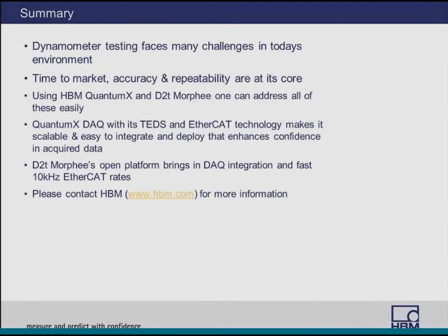The only thing is today we can communicate directly with the ECU. So that means the ECU is usually running at up to 10 kilohertz, maybe more. So we need to communicate with that ECU very fast. Also, we have other applications such as the simulation or the models which are running at a very high frequency. So in order for those models to perform fine, we want to run at a very high frequency, and that's why 100 Hertz is not enough anymore in today's testing environment.